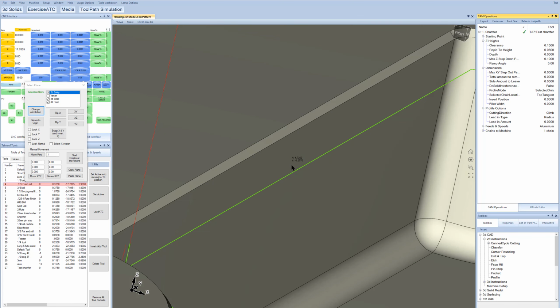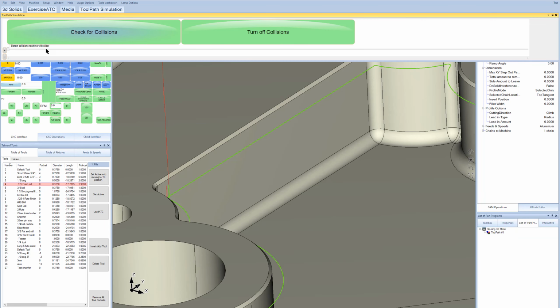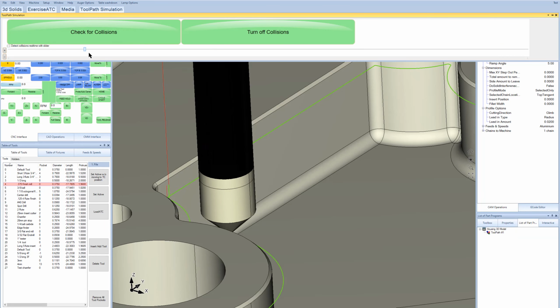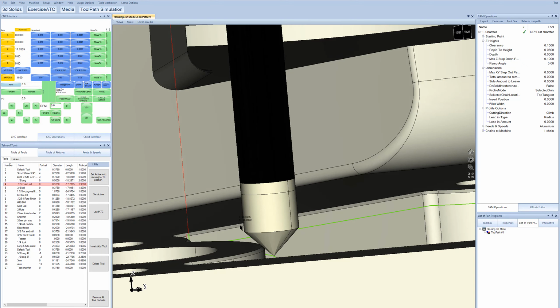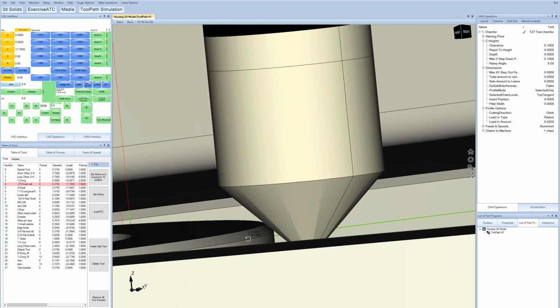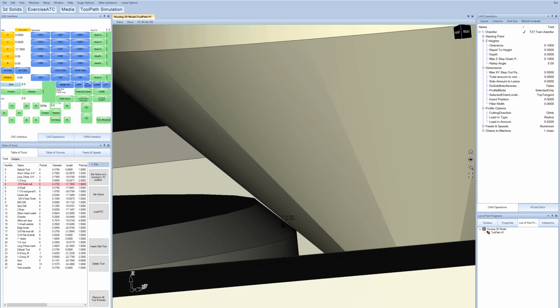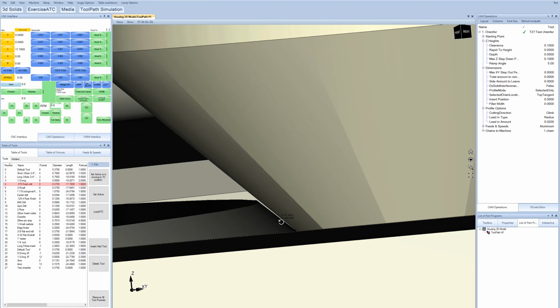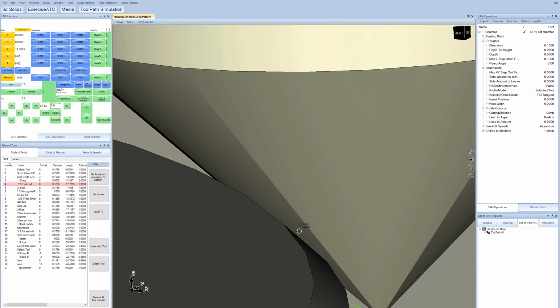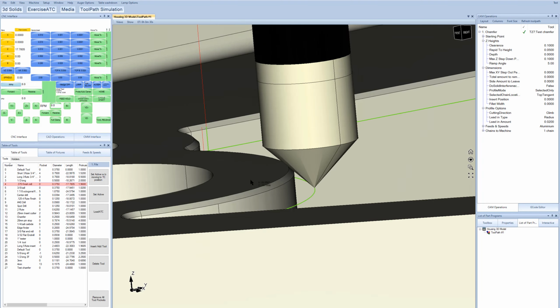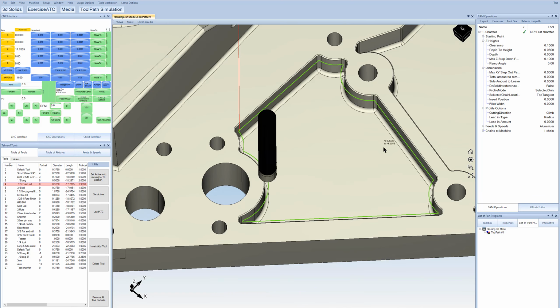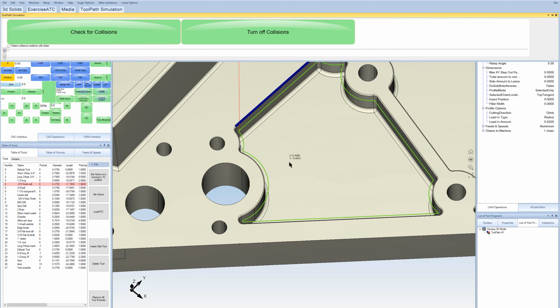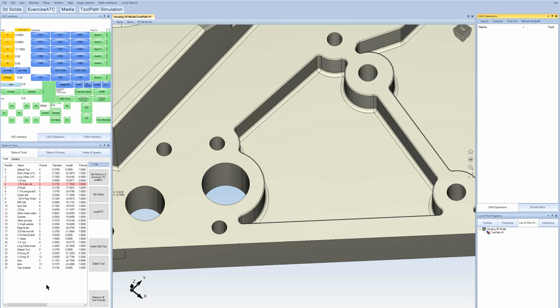Okay, and then we get something that looks like this. So let's toolpath simulate that. And now you can see as it comes around, our cutter is exactly on that edge there. And it kind of looks like the chamfer in the model is not 45 degrees, but that may just be a graphical thing. Yeah, so I'm going to assume that's okay. All right. Now we'll talk about one other scenario real quick that is not a chamfer at all. It's corner rounding. Okay. So let's see if we can do that real quick.